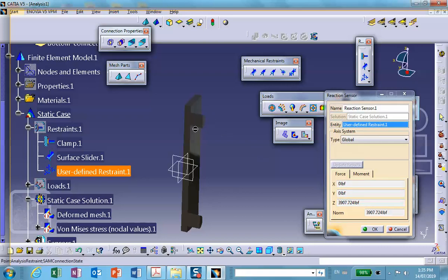In order to find the total load needed to achieve this deformation, you have to multiply this thing by 2. So the answer to this problem, you have to multiply it by 4. Because this is that quarter of the model. There is also the one adjacent to it, so that doubles it. There is also one on the other side, so that thing is multiplied by 4.